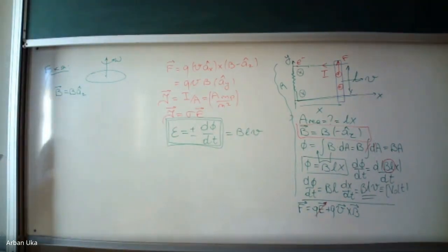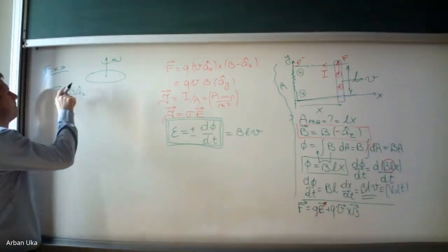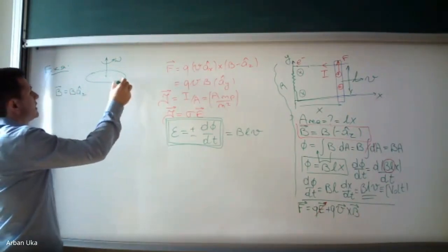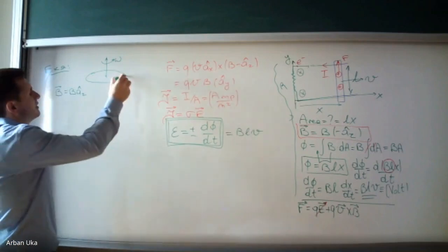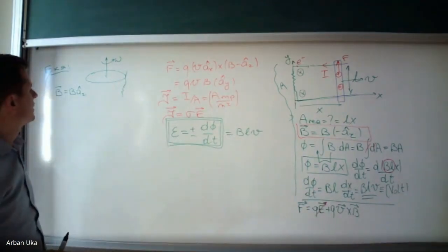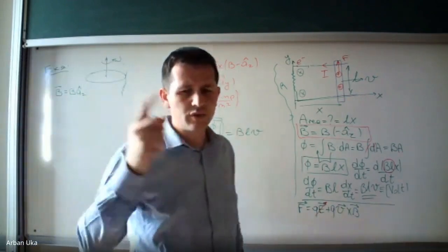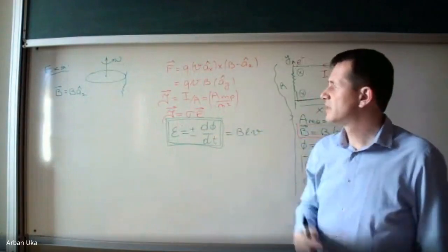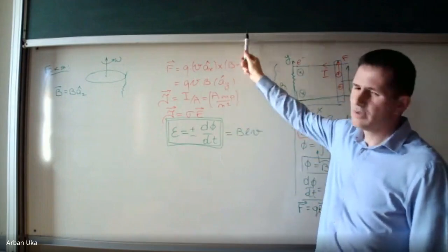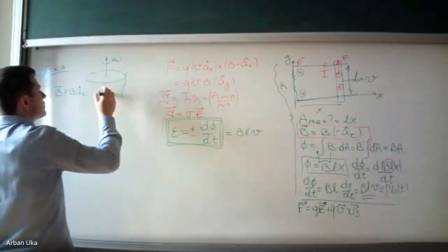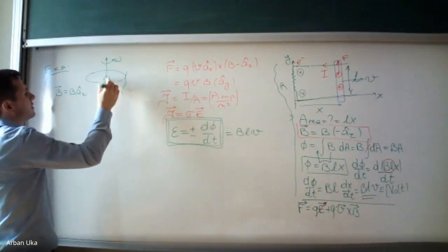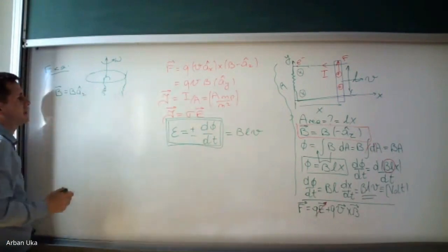Okay, so this is the magnetic field, and what we can do is connect. If this is in motion, we can use a wire with a spring that is touching the outer edge of the rotating disc. We just need to touch it. We cannot fix it because the wire would be wrapped around the disc. So imagine you're making a connection to a circuit from the outer side, pushing like this. That means you are creating a current. At the same time, you can also use a spring system to touch the bottom of the center here. So at least you can make connections with systems that are in motion, and then